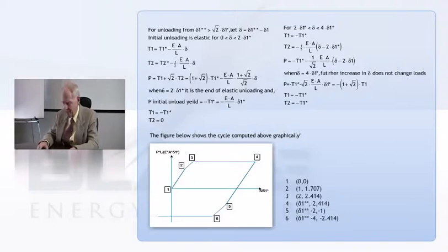And the remarkable thing, I would say, is that if you look at that curve, we've taken that load P and we started at point 1, and we got to point 2 where one of the bars, the central bar, yielded. So the resistance to increasing load drops off.